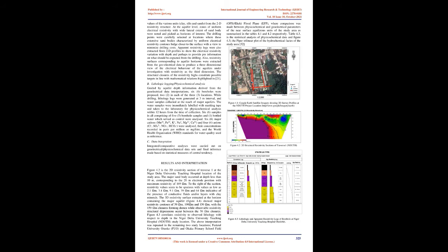Materials and method. A. Geoelectrical investigation. PASI Earth Resistivity Meter Model 16GLN was used for data acquisition, and Wenner-Schlumberger survey geometry was employed using a 21 electrode system with spacing of 10 m or 5 m in some profiles depending on the availability of space. 4 reels of wire, 2 potential and 2 current electrode wires each provided with crocodile clips. 2D geoelectric resistivity profiles were run in 3 locations, 4 in the premises of the Niger Delta University Teaching Hospital, NDUTH, Okolobiri as shown in Figure 4.1, and 3 profiles each in Okaka/Ikaki communities and the Federal University Otuoke, FUO, respectively.